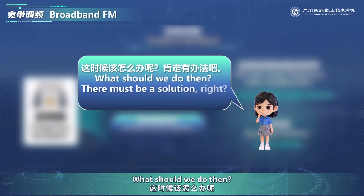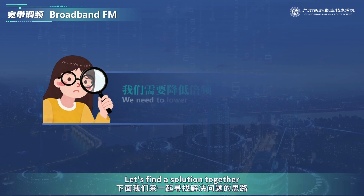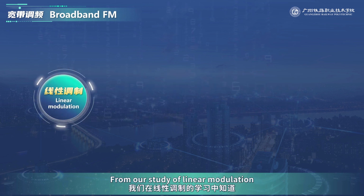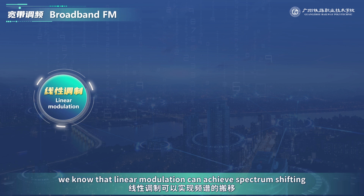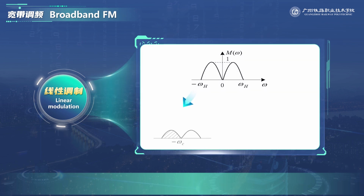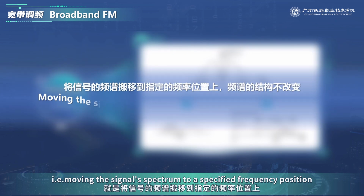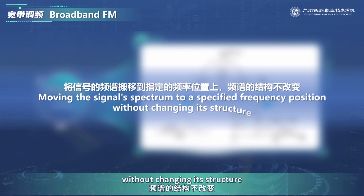What should we do then? There must be a solution, right? Let's find a solution together. We need to lower the carrier frequency after multiplication. From our study of linear modulation, we know that linear modulation can achieve spectrum shifting, i.e., moving the signal spectrum to a specified frequency position without changing its structure.